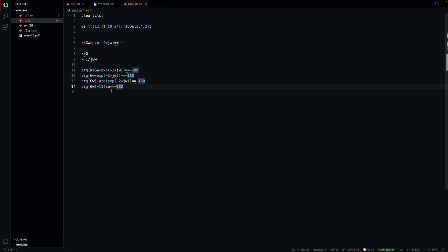It is interesting because we can see that the phase condition depends on omega. If we plug 10 to the power of 3 into omega, like infinity, this will become minus infinity. So the phase plot will be changed drastically in this case, because omega is in the equation, and if omega increases, this whole thing will decrease and tend to minus infinity. So a system with delay has a way different phase plot than usual. So that's something to note.